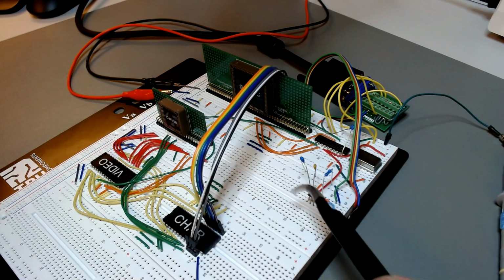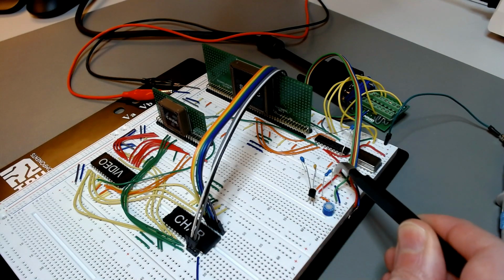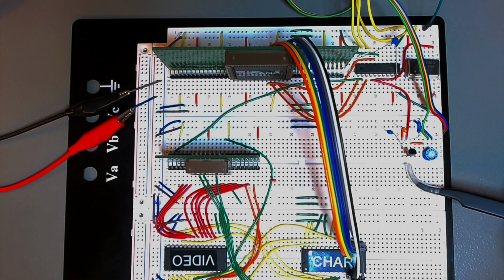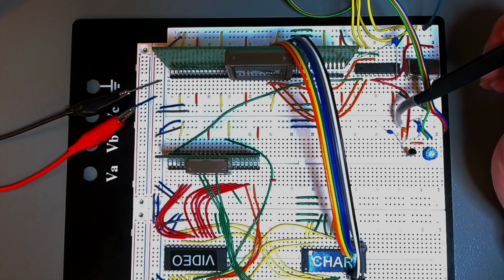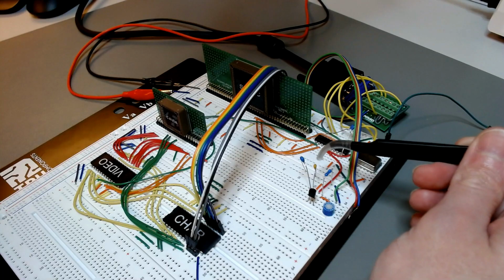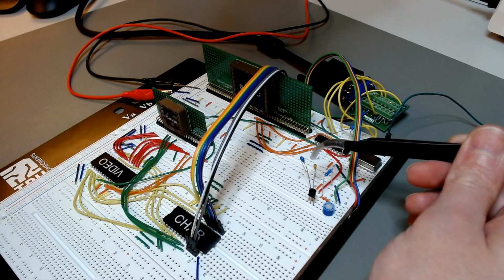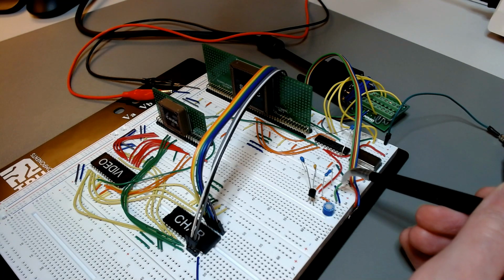This is a simple analog circuit. The signal to be boosted comes through this red wire into the base of this transistor. On the collector of the transistor there is a connection through this little orange jumper straight to the 5-volt power rail. There are two decoupling capacitors in there, and this resistor is connected from the emitter to ground.